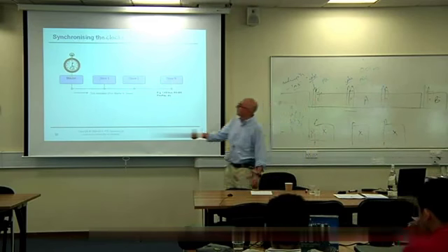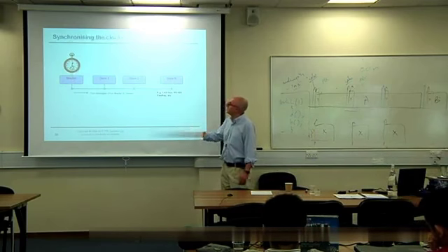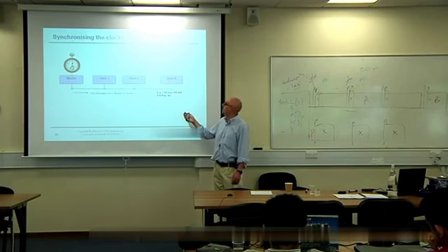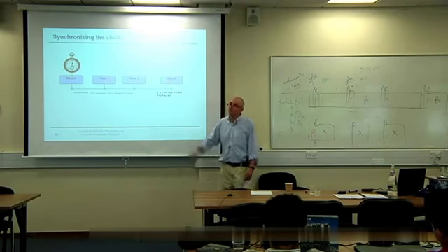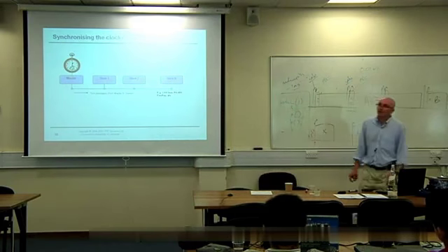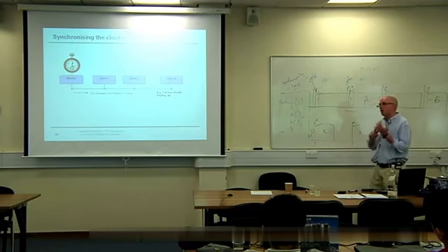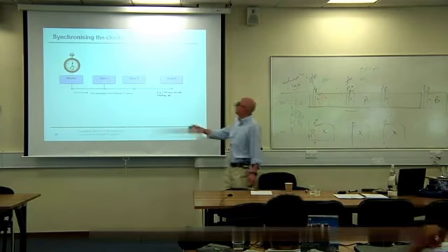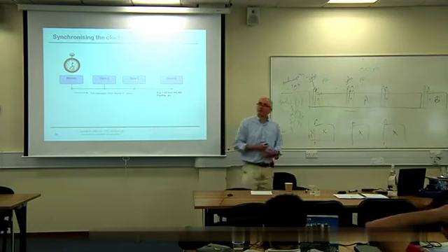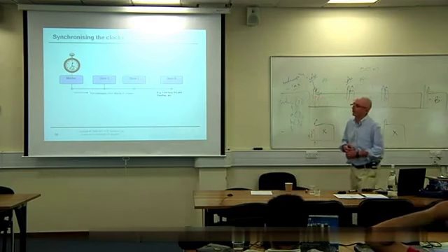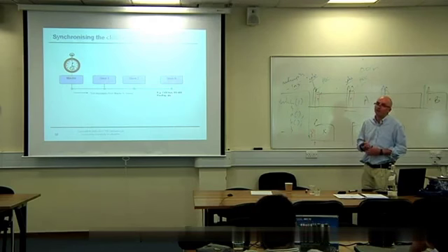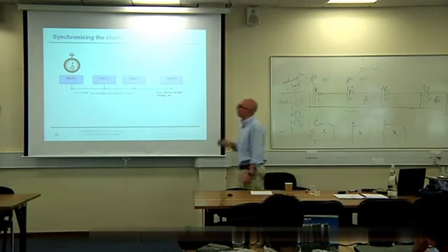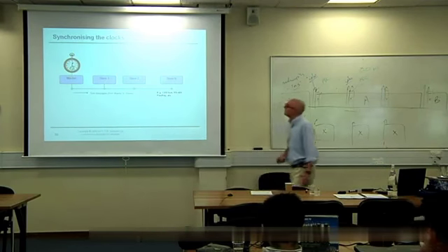So this generates periodic ticks. This sends messages. The arrival of these messages generates interrupts on these nodes, and these interrupts drive the scheduler on the node. So the scheduler is pretty much the same as you've seen before in sessions up until now, but the interrupt source, there's no timer running on these. The interrupt source is the CAN bus in this situation. Still one interrupt source per processor. We just use a different source to drive the scheduler in this case.